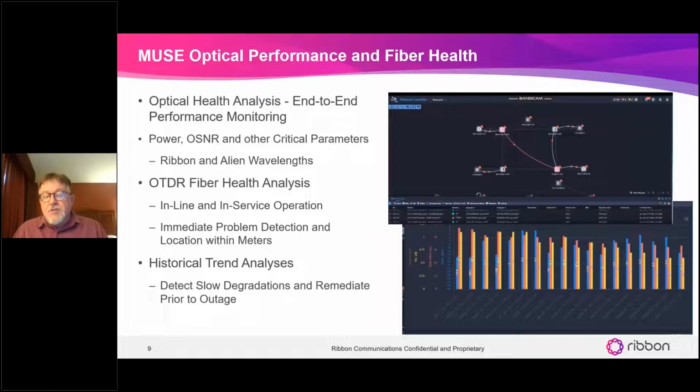issues, both polarization mode and chromatic dispersion, and then as well on the DWDM side, what we call nonlinearities, right? Other errors that can take place. Generally, these issues can be engineered out at the beginning of a network build, but outside plant changes, right? Temperature changes, moisture changes. Sometimes people decide to roll dump trucks over shallow direct buried fiber, and that causes problems. You just never know what's going to happen, right?